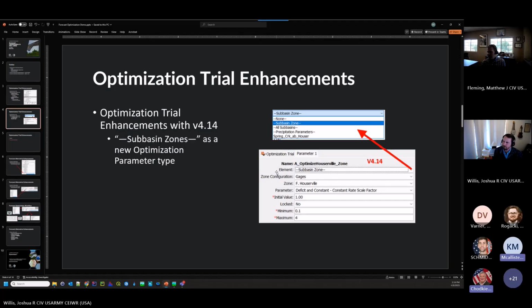Interesting. Yeah, because when you're setting up these optimization trials, you said it's at observed flow locations specifically. So let's say that you're already doing something similar to the forecast initial base flow, where you're actually setting the upstream boundaries to that gauge flow value. How do those interact when it comes to using both of those together?